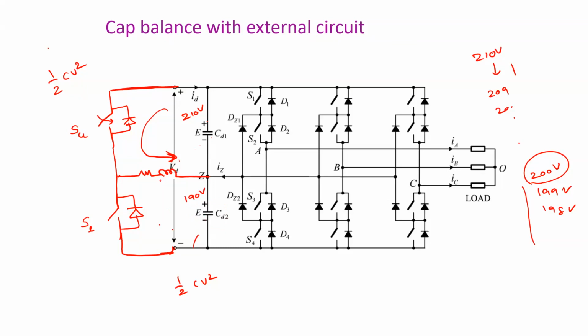Okay. So how exactly will it transfer? If you turn on this lower switch, the current is moving in this direction, right? The inductor will not allow a sudden change, or will not change this direction, so it will form a circle here. Understood? Now this switch will be closed and this diode will become forward biased. Therefore, whatever energy is stored in this inductor is transferred to this capacitor.